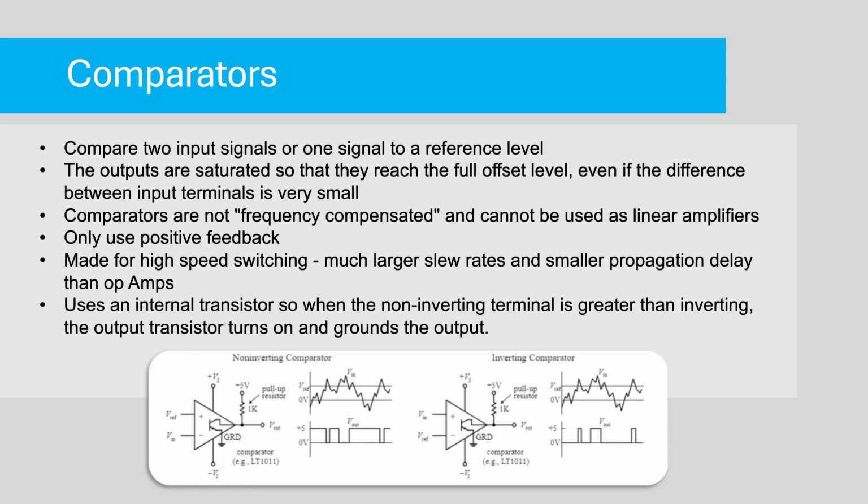So that's something important to note, where all of the inputs are going to be positive. Even when we see it dropping, like it goes above reference, it drops, it's still staying positive the whole time. And this just allows us to have very predictable DC output. We're taking an AC input essentially here, just a jagged wave coming in, and we are outputting a very clean high-low signal. And that's why only using that positive feedback gives us that benefit.